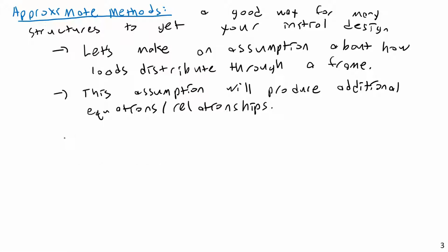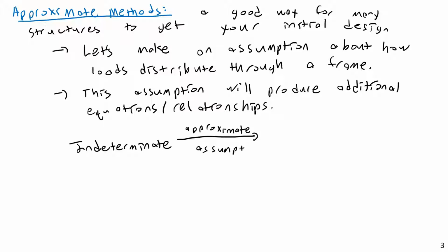So again, just like with the force method, they are a way of taking an indeterminate structure and turning it into a determinate structure. We take this indeterminate structure, put in some approximate assumptions, and on the other end, we'll have a determinate structure. You would not want to rely on just these methods alone for designing a life-critical structure, but as a starting point for your analysis, it can be a very good method.